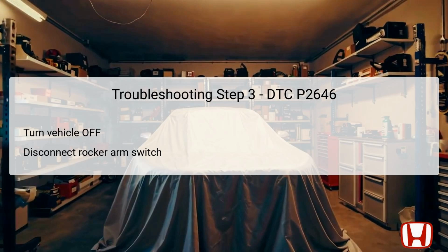If the current conditions do not match the threshold values, however, the technician should proceed to the next step for further investigation. Here, the technician must turn off the vehicle and remove the rocker arm oil pressure switch, utilizing special tools to connect the rocker arm oil pressure switch to the oil pressure gauge adapter. This step is crucial in directly measuring operating oil pressure during engine function.